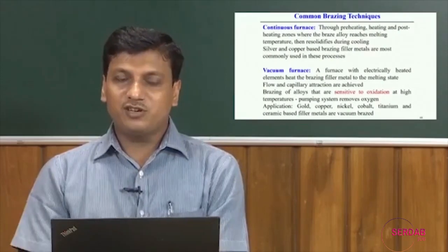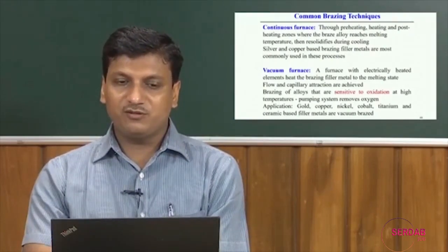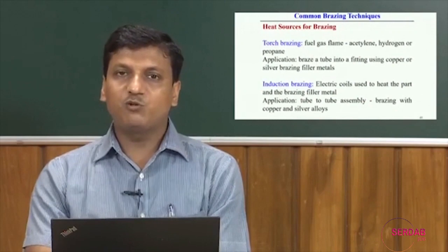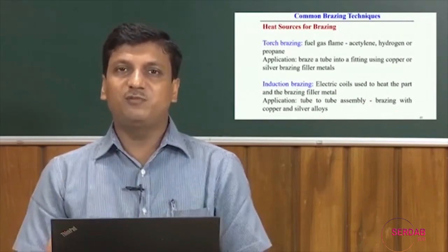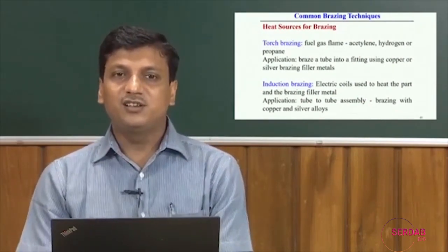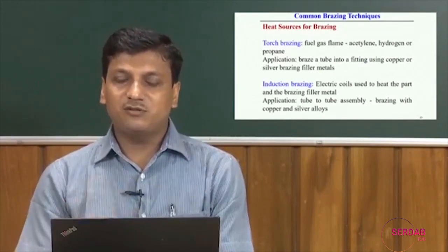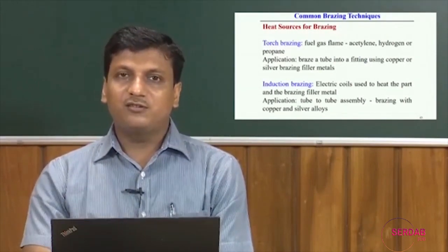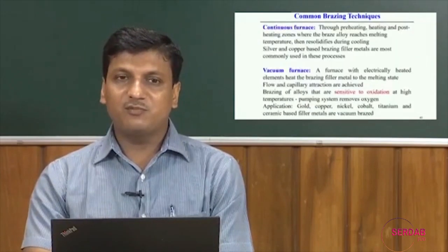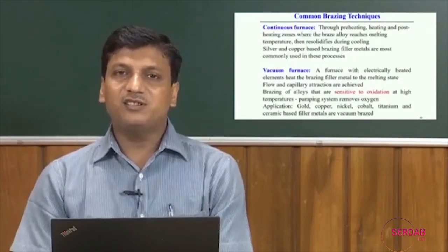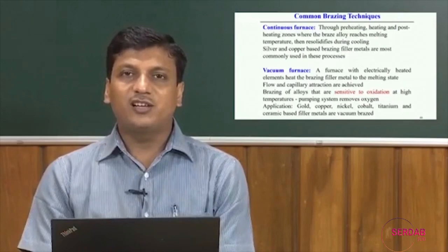If we consider all these different brazing techniques, the simplest application is torch brazing. Induction brazing is the more controlled approach, where we can control the temperature. Then continuous furnace and vacuum furnace are other brazing techniques.